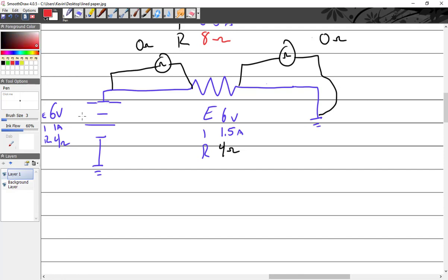I'm going to use red here. But I measure it. Now I measure it, and I'm like, well, that's kind of funny. I'm getting like 5 volts here. Well, you know what? Let's not even worry about that. Let's go back here. Remember my question? I said, what is the resistance of this wire? How can I determine the resistance of the wire? A minute ago I said it was 0. What happens if I put a voltmeter here, and the voltmeter says 0.5 volts? I put a voltmeter here, it says 0.5 volts.